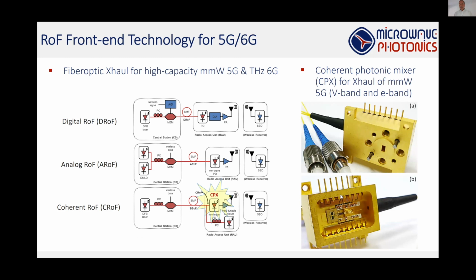And then you have the antenna chip here, which is in this case connected to a rectangular waveguide. So the output here is a rectangular waveguide. So basically this antenna provides the connectivity between the photonic chip and the rectangular waveguide. So you can directly attach this component to the antenna. So there's nothing in between the optics and the RF, in this case, than a balanced photodiode.